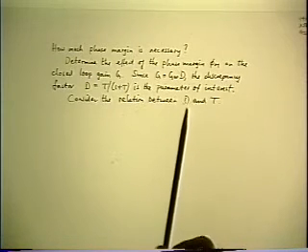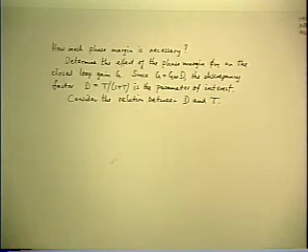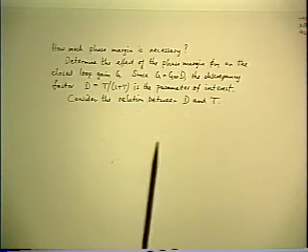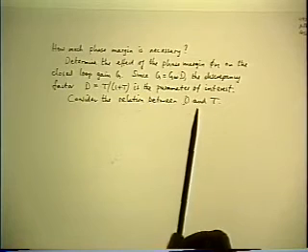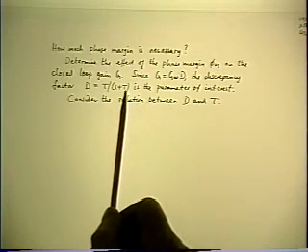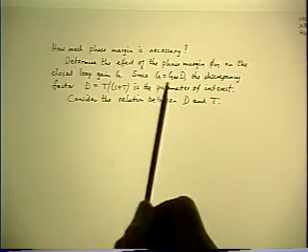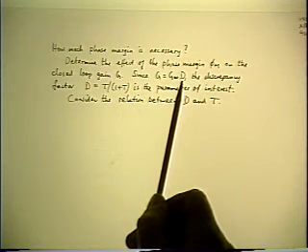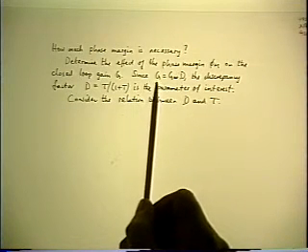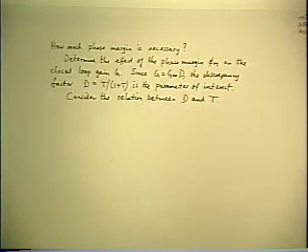So the proper question is not just as some sort of arbitrary absolute number, how many degrees of phase margin do you need? The proper question is, what is the relationship between the phase margin of T and the shape of D, which determines the shape of the closed loop response? That's the real question to ask.